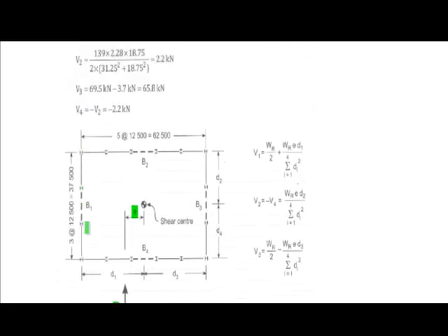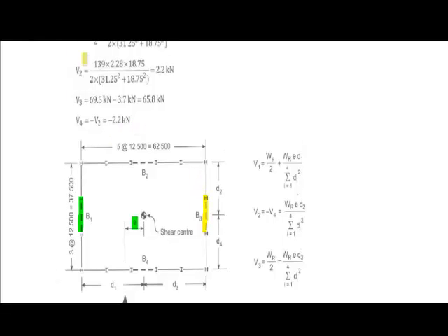And what you'll find is more force goes into this brace than this brace, and in fact some limited force is also going to go into these braces, because you're going to have a bit of torsion in your building. So when you're designing this, the largest force is going to be on this one.